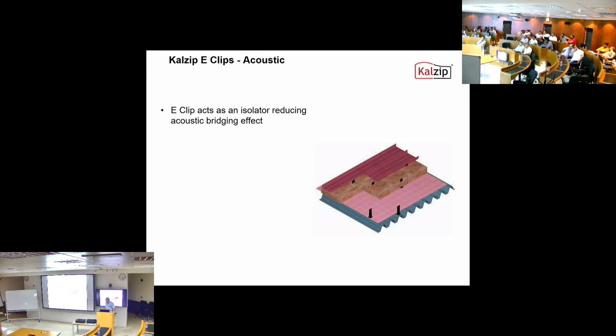For you, the concept is how much sound reduction index you are going to achieve. That's one way. There's sound reduction. We can consider sound absorption as well. So we break it down to four: sound reduction, sound absorption, impact noise, and flanking sound.